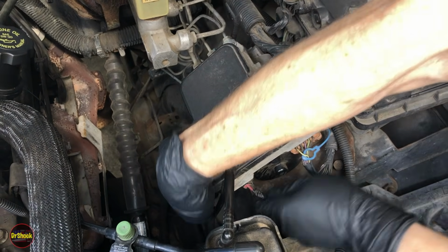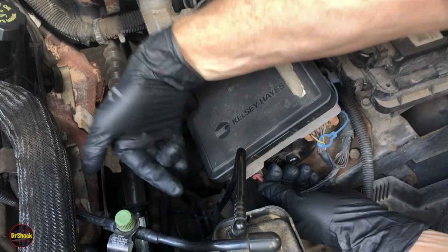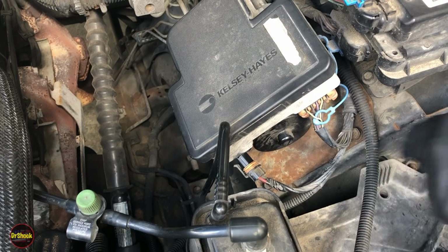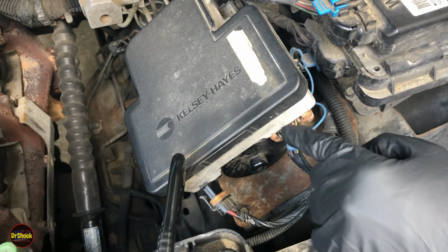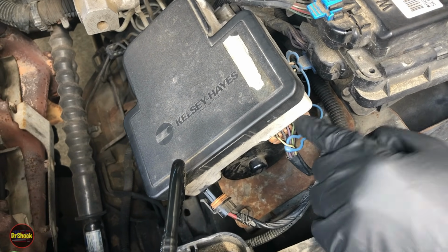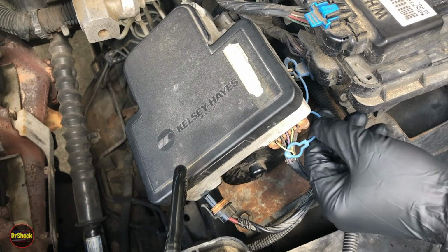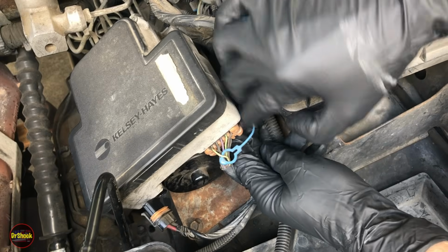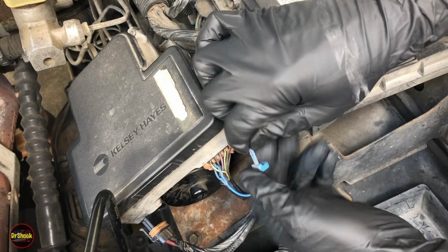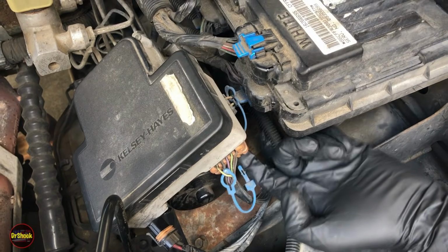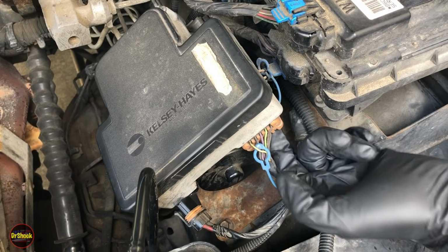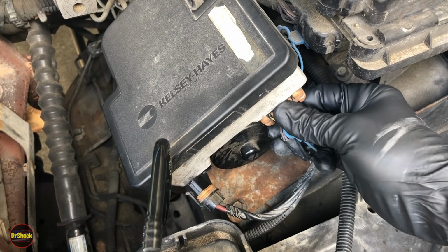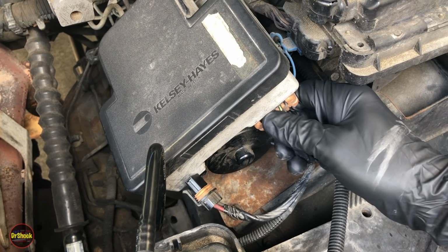So we'll start with our C3 connector that we did all of our testing on. Remember to lift up on the retaining tab right here and pull it off. Then we're going to take this EBCM harness off here. It's got a retaining clip to help keep it from coming loose. You're just going to take this and pull it out, right? Just pull it out. And then underneath here, you're going to find there's a squeeze type prong that you use to get this guy off.